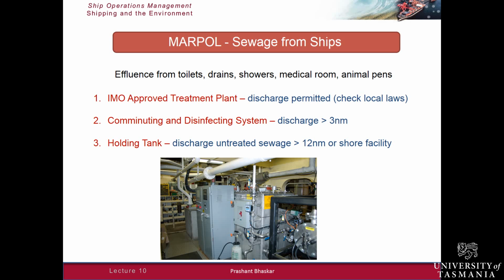Secondly, if the ship has a comminuting and disinfecting system, not a fully IMO compliant treatment plant, then it can discharge the sewage at a distance greater than 3 miles from land. Otherwise, it must have a holding tank, and then it can discharge the untreated sewage from more than 12 nautical miles, or it keeps the sewage inside the holding tank and discharges it to a shore facility when the ship is in port.